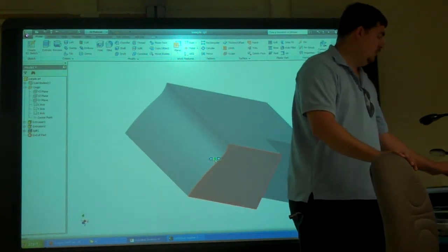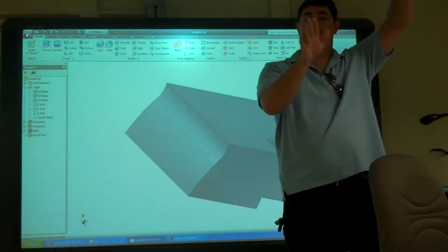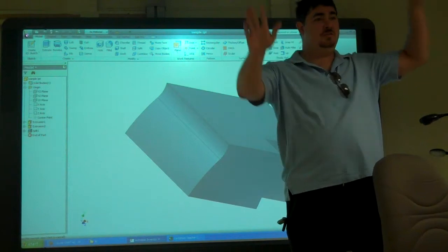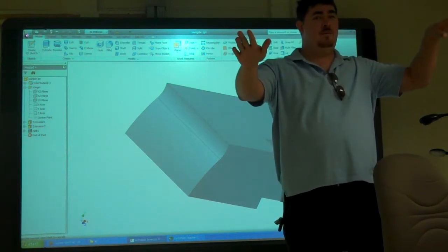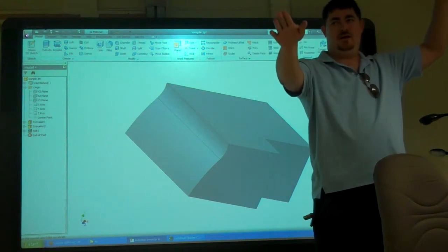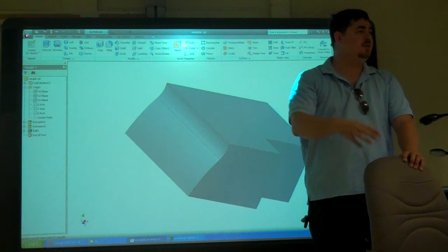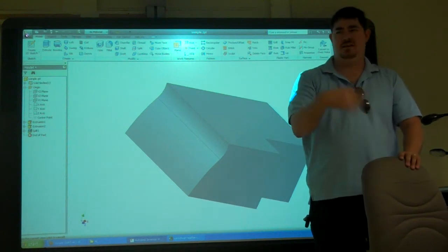And so you can use, like I said, planes or anything. So if you wanted to make an oblique surface, so it's angled on two different faces, you could draw it as a box, set up a work plane to kind of cut the corner, and then use the split just on your work plane and not have to do any sketches. So it kind of saves a step.